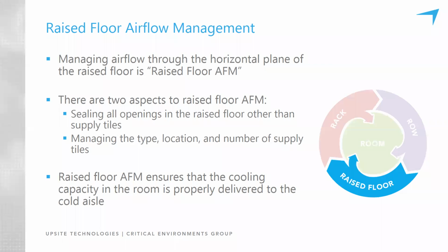With regard to the floor, and assuming you're in a raised floor environment, it's all about managing the distribution of the cold supply air and giving it a clear path to where it's needed most and preventing it from going to areas where it will be wasted. So using things like floor grommets, fire retardant foam, and other floor specific barriers, those are the best products to use to seal gaps in the floor. And this allows you to focus more on the proper placement and size, percentage of free airflow of perforated tiles used to enable the supply air to reach the IT load.